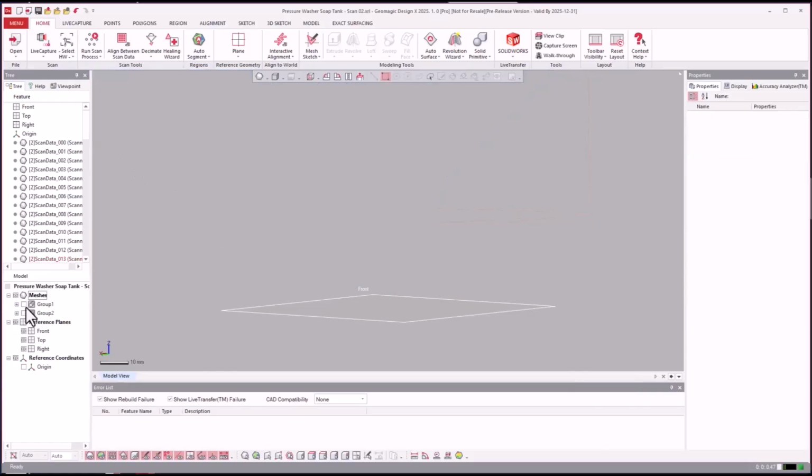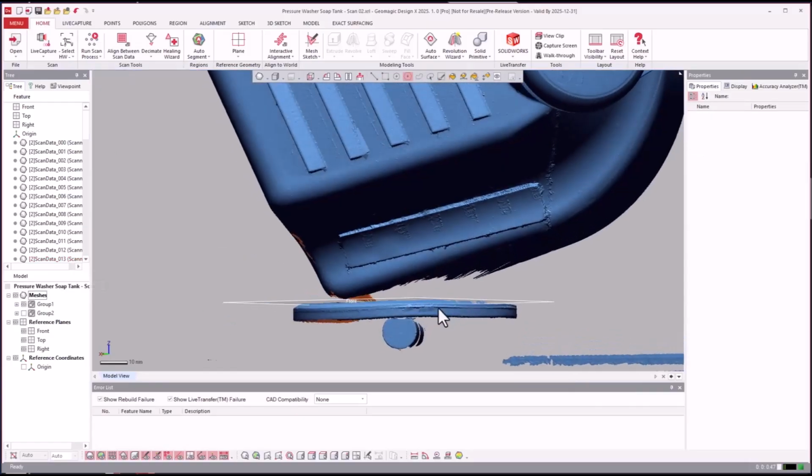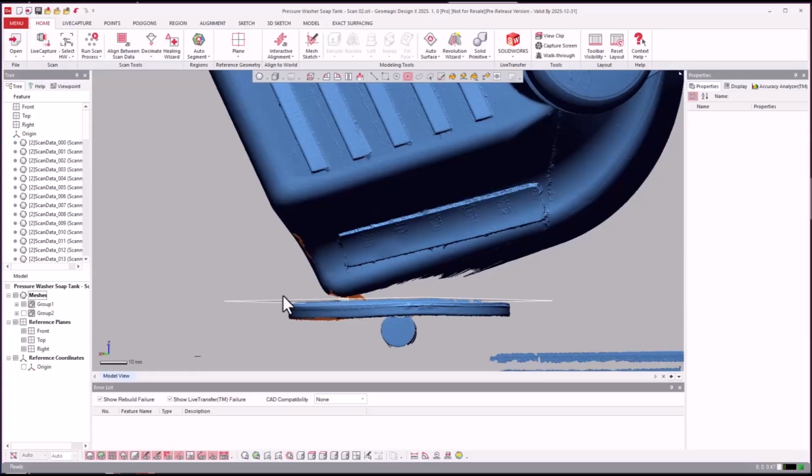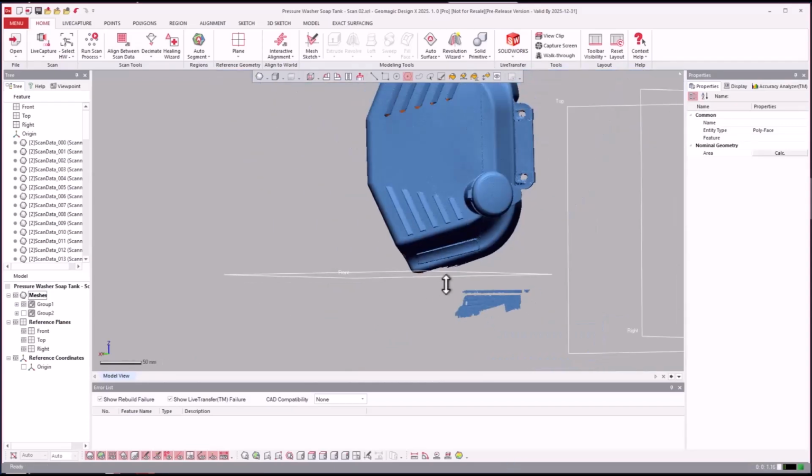So there, I went ahead and deleted some of that information, and then you'll see here, I'll just rotate this and delete some of this now here. And I'm using certain tools that we've talked about before. Right now I'm using that polygon selector tool, making sure I have select through on, because that's a popular mistake, is leaving back faces on to where you don't actually select through. And sometimes it's just easier to use this polygon selector tool.